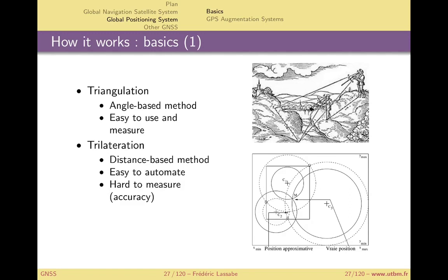So then how does it compute the distance, the location? You have your signals, you have the time. From the time you get the distance between your GPS chip and each satellite. And then you have to compute the location. So you hear a lot of triangulation to determine the location of the chip, but it's not the proper method. It's not what the GPS uses.